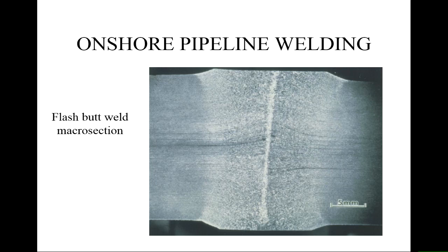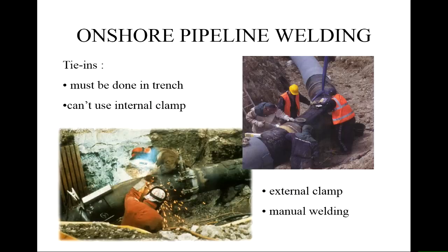Not usually done on pipes, because then you'd be shortening the length of the pipe and distorting the shape of the pipe. So we rely on very good cleaning and preparation of the surface prior to welding to avoid those oxides that are there. Can be done, can be a good joint. Much less distortion than compared to an arc weld.